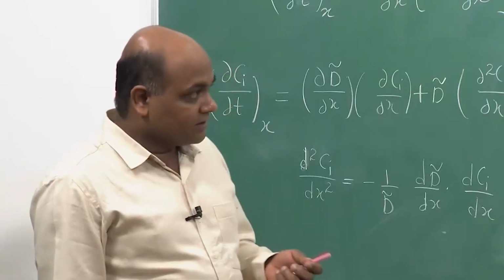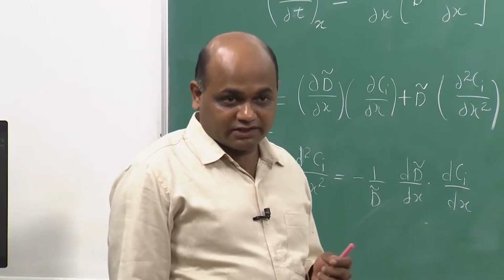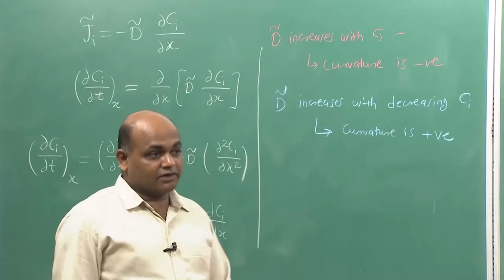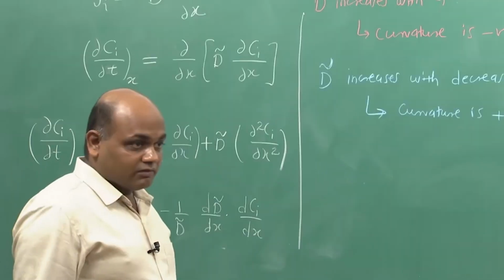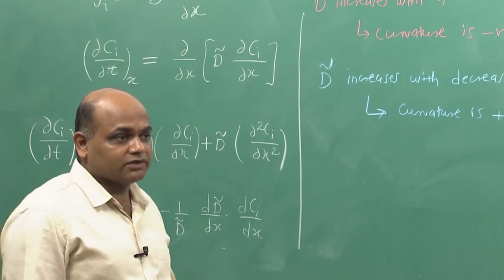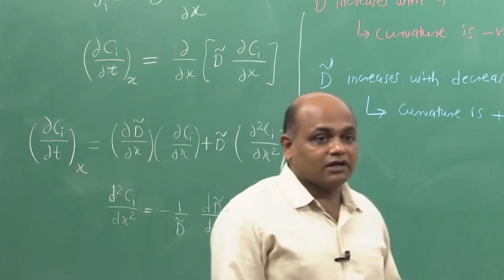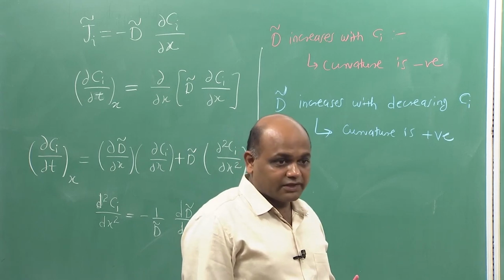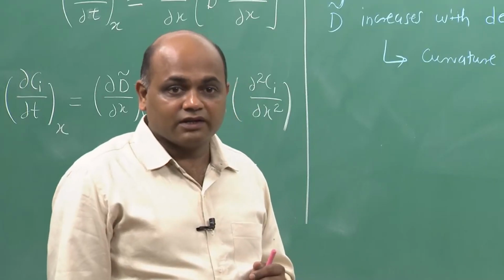Now, when concentration does change with time, that is a non-steady state condition. So, we will solve this equation for different boundary conditions and initial conditions. We would like to assume d tilde as constant, then we can have an analytical solution. So, we will assume d tilde constant, so that we have an idea how the concentration profiles will behave for different boundary conditions. Okay, any doubt? Question? Yeah.